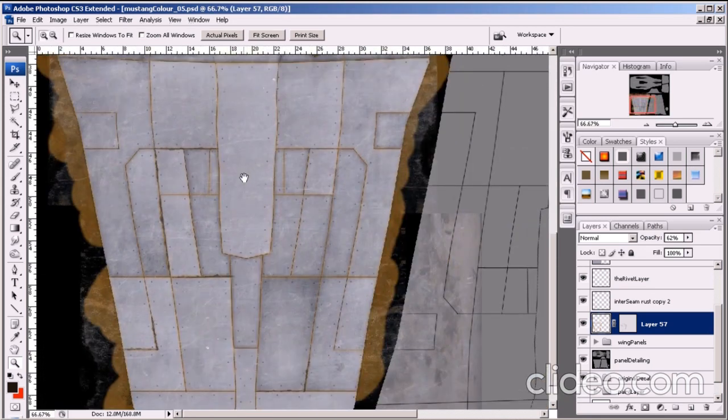But having done that, we've got that certain level of it that's just too much. It's now just looking too over the top. So I'm going to work back in again as we did before, using the vector mask with a black paintbrush. Okay, now we're not going to want any of the edges down here orange, i.e. with rust on it, because these connect to each other, these two edges, and there shouldn't be a visible seam there.